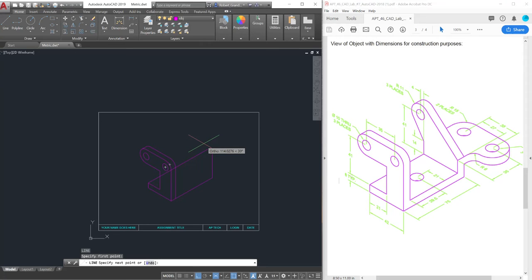So I'm going to type in 60. Is that correct? Oh, 67. Math is horrible. So let's do it this way. I'm going to type in a parenthesis symbol, minus, 75 space 8, and an end parenthesis. So you can see what AutoCAD's doing here is I'm waking up the AutoLisp evaluator, and it's going to evaluate this expression and return to me the value. And now you can see it actually returned to me the value of 67.